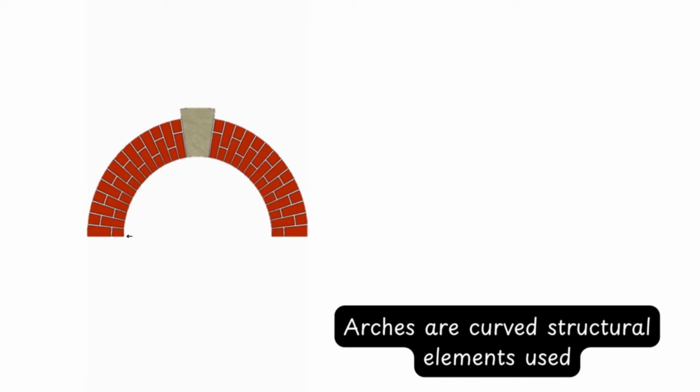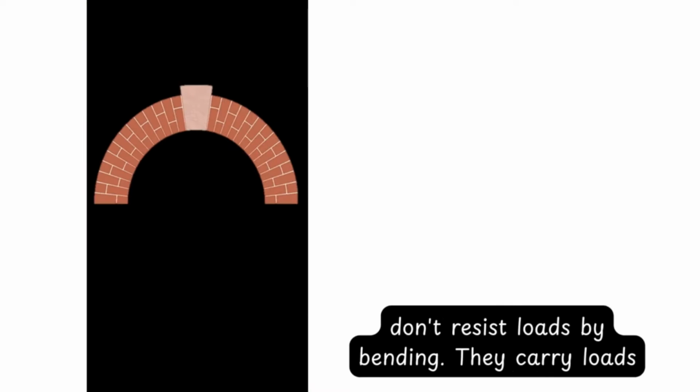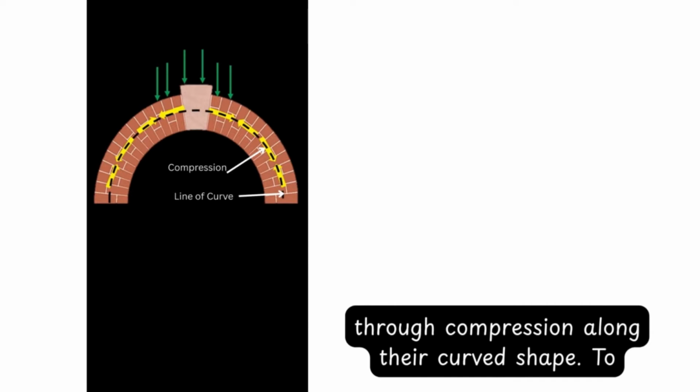Arches are curved structural elements used to span openings like doors, bridges, or windows. Unlike beams, they don't resist loads by bending. They carry loads through compression along their curved shape.